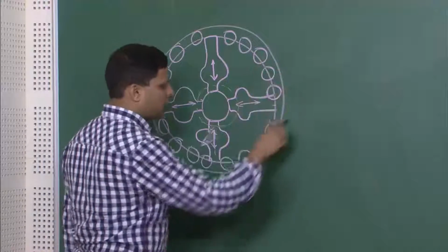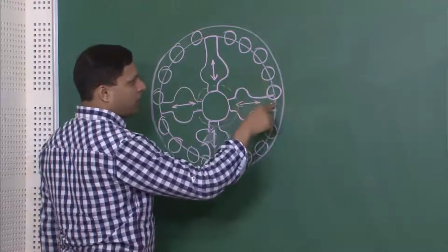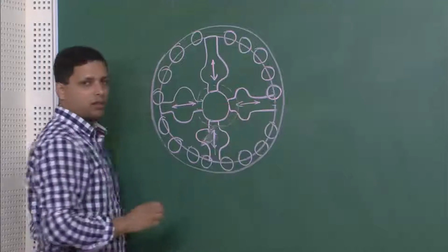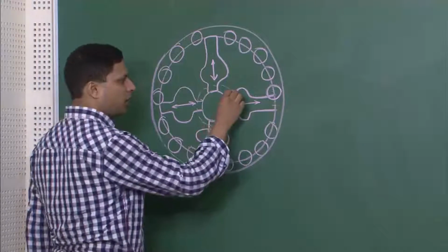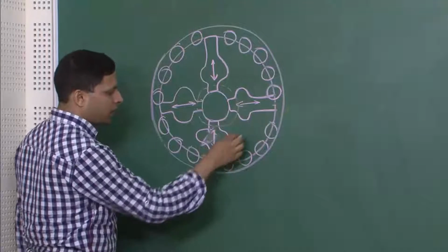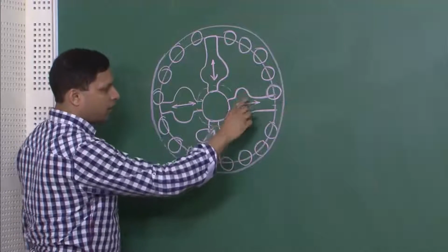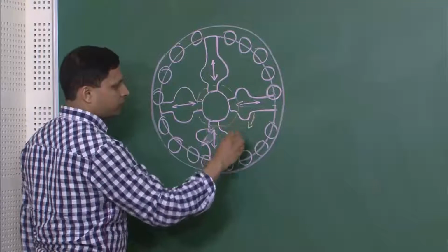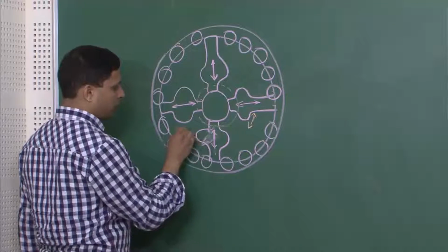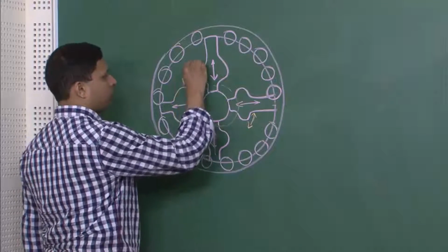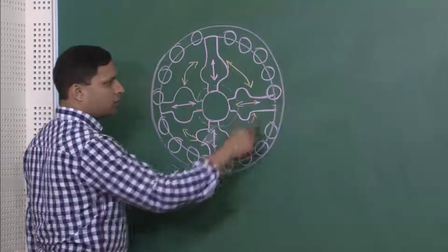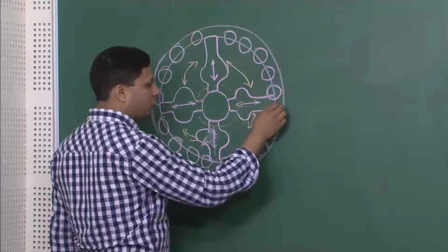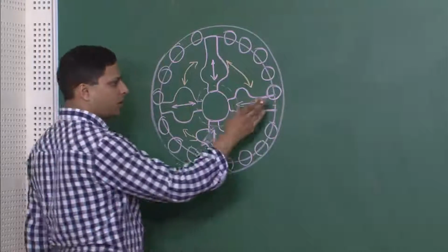Now, when it starts to rotate, every time a ball comes over here, it will push this hammer inside, and it will hammer this wire at this point and keep rotating. So, this whole thing is also rotating at the same time, and also the spheres are rotating, which ensures that this hammer operation is carried out.